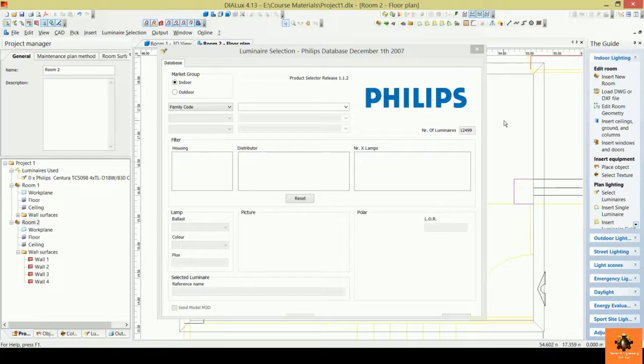So the fluorescent luminaire will be a suitable one. And also let's select it to be a fluorescent luminaire 4 times 18 watt. So we need a luminaire which includes 4 lamps, and each of them is rated 18 watts, which means that it's a TLD lamp, not a TL5 lamp. And also its length is 60 centimeter as it's 18 watt.